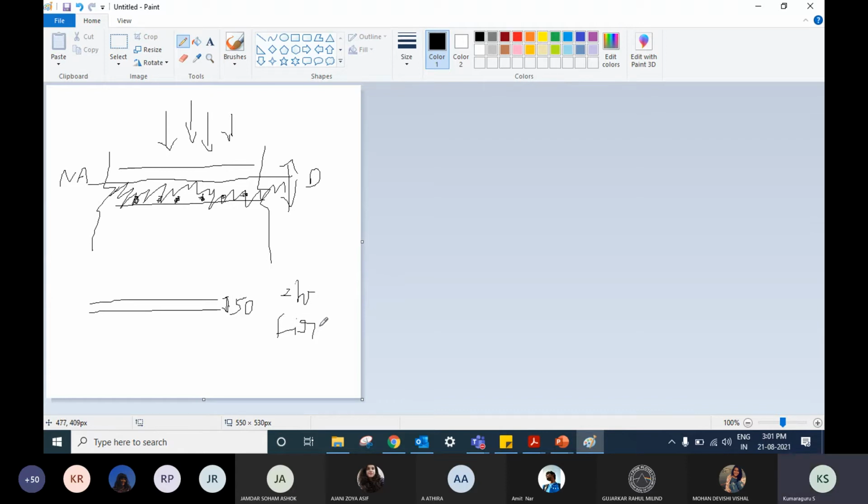So you need a sufficient amount of thickness. It can stand for 2 hours. So this 50 mm thick slab won't stand for that long, because the fire can reach the reinforcement bars inside very quickly, in some minutes itself. And when the reinforcement reaches its critical temperature, it is going to yield and lose its strength. So it's going to bend, deflect, get damaged and fall down.